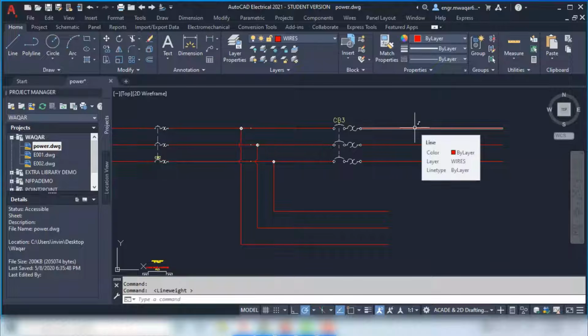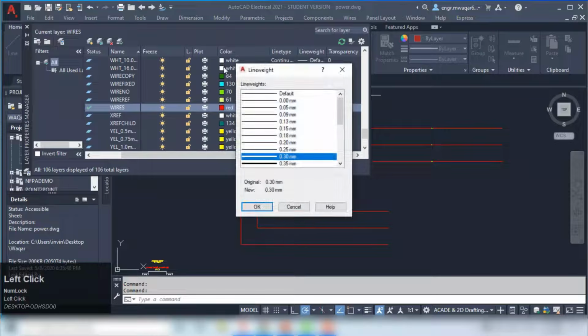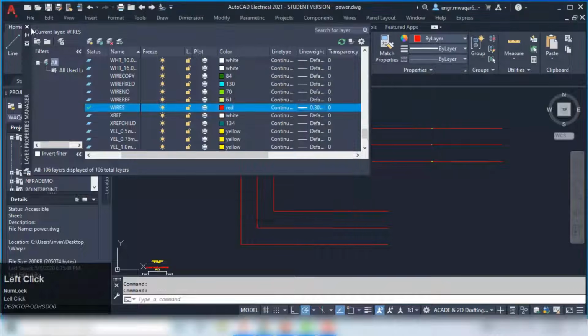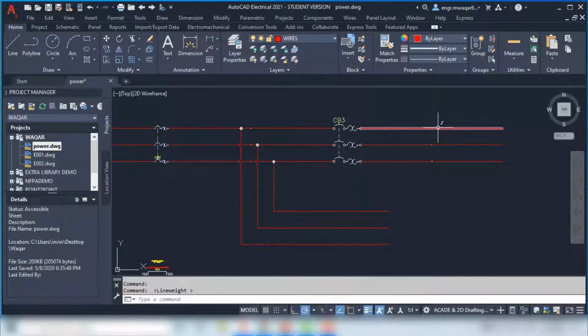Right. So if you plot your drawing and all your lines look thin and uniform, you've probably forgotten to toggle the show or hide line weight setting. It's a common rookie error that really trips up quality control. That's a perfect example of a tiny setting that can completely derail a printing job.